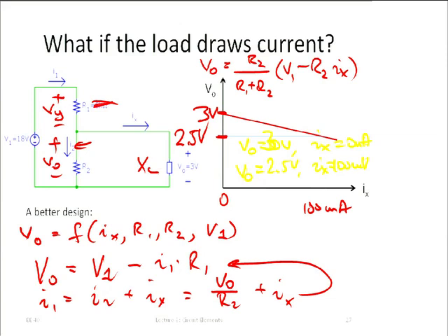Okay? And then we get 2 equations, because we have 2 conditions. And these equations have how many unknowns? 2, which are R1 and R2, right? And then, of course, we can solve for R1 and R2. And once we solve for R1 and R2, well, we have solved our problem. Did I write what R1 is? Oh yeah, I did write it for me already. I did solve it. You can try it yourselves and see whether you get the same thing or whether I made a mistake. R1 is 150 ohms, and R2 is 30 ohms.